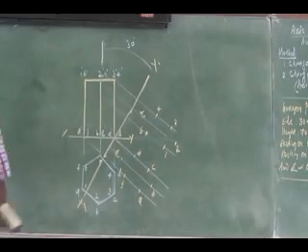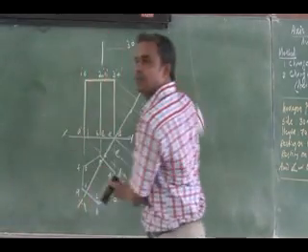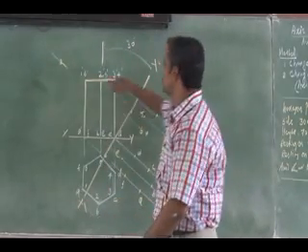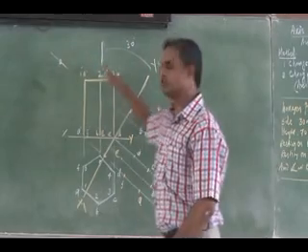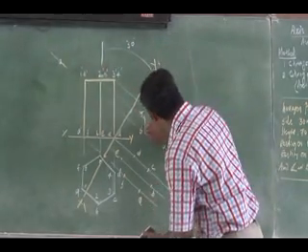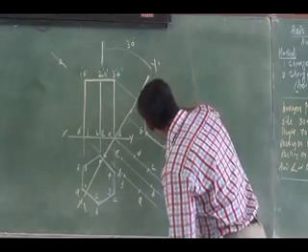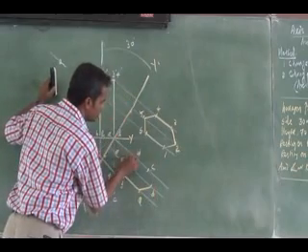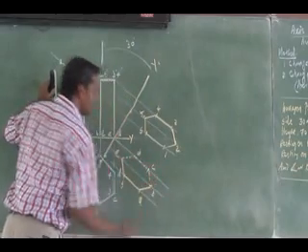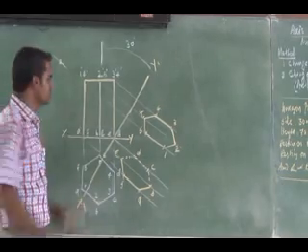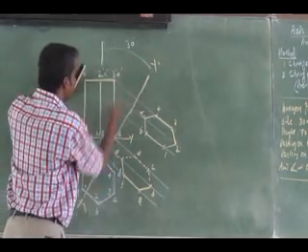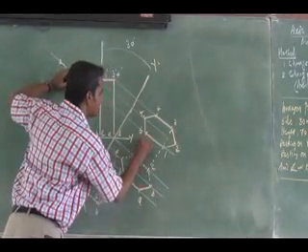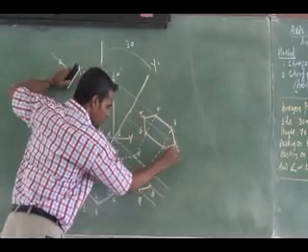This is how I will be getting my final top view. Here, you have to look from this direction. This is the top view direction, perpendicular to the new reference line. So which is the fully visible base? This one. This fully visible base will be connected with a continuous line. The partially visible base is this. So this portion is invisible, hidden. Right. Then I have to connect the side edges, which are the bottommost edges to the new reference line: 3, 4 and CD. That I can join as a dotted line. Right. The other edges will be fully visible.